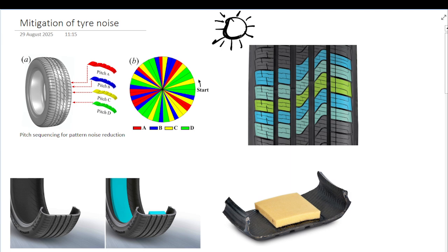It's like a drum with many welded plates. That's what you have to think now for my drawing. So if you roll this on the surface, you then hit, and if you measure this, there will be a single frequency band, there will be a higher amplitude because you are hitting like tuck, tuck, tuck, tuck. Then this will produce a noise at certain frequency.